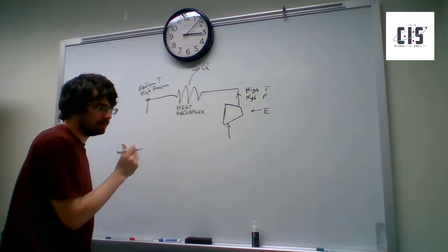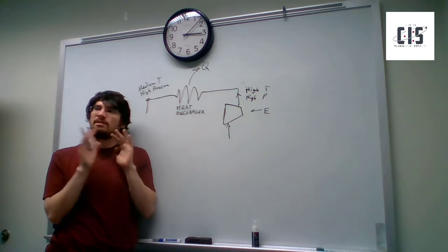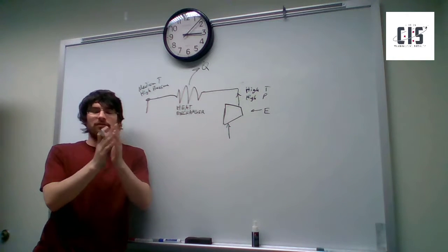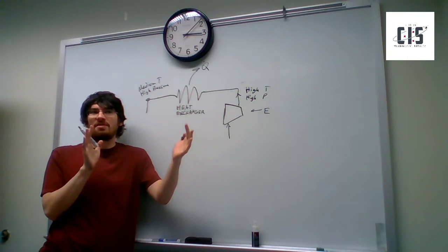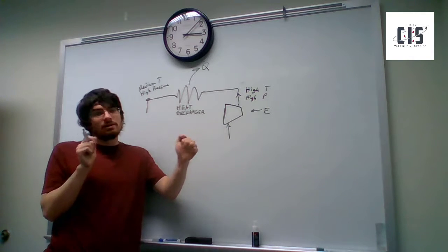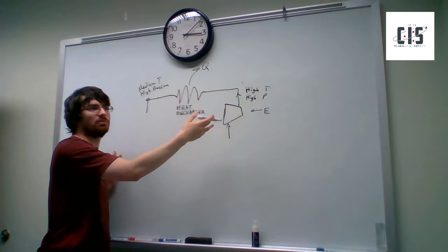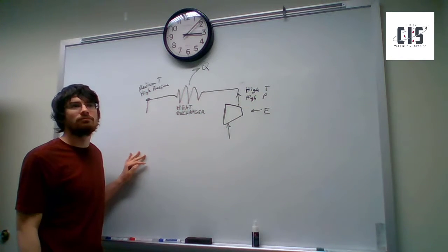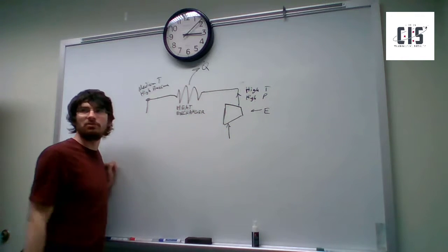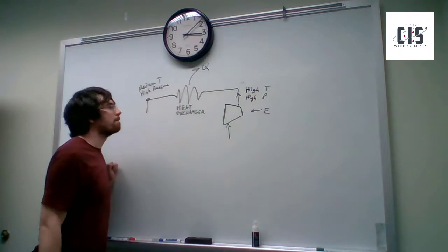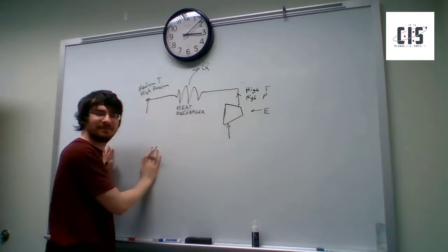So one nice thing is that if you compress a gas quickly, it heats up and it increases pressure. If you then release that and allow it to open again, the pressure drops and the temperature also drops. If you were to do that right here, and both systems were completely 100% efficient, you would get back down to the same pressure and temperature you started. Exactly. But we are now at a lower temperature. Ooh. Lower temperature than that.